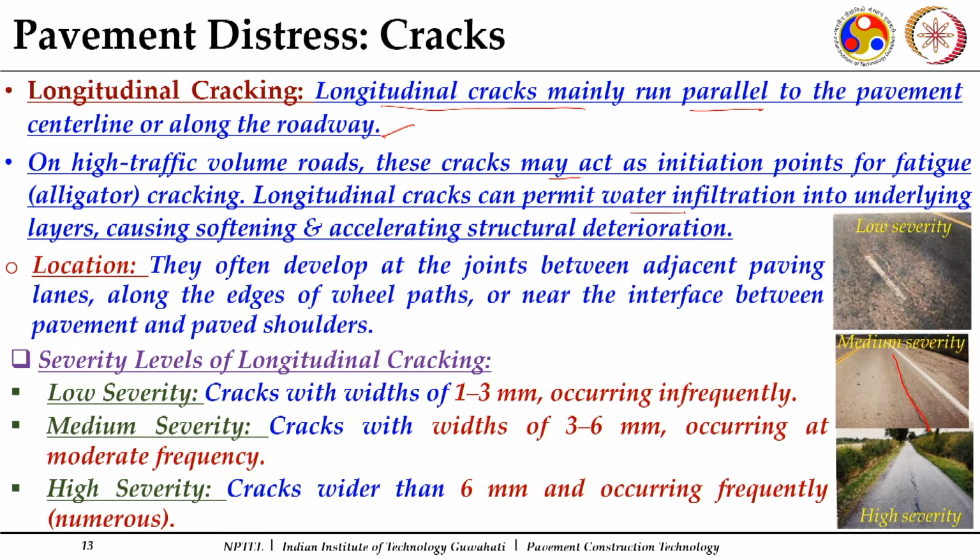Longitudinal cracks can permit water infiltration, because if the width of the crack is more, even fine cracks, it allows water to penetrate down into the underlying layers, causing softening and accelerating structural deterioration. So, this raises a major concern. If the crack width is good enough to allow water to penetrate down, then it raises other concerns also.